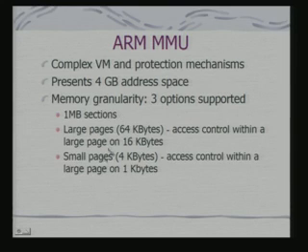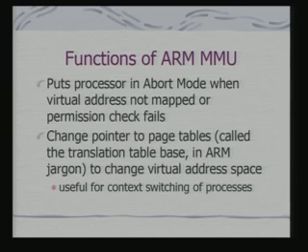So, these collections of pages or sections are being referred to as regions, okay, and a region can consist of a number of pages, and the OS keeps track of the regions and the pages for the purpose of allocation to different processes. And what does the MMU do for protection? It defines what are called various kinds of domains, and using domains this protection policy is implemented.